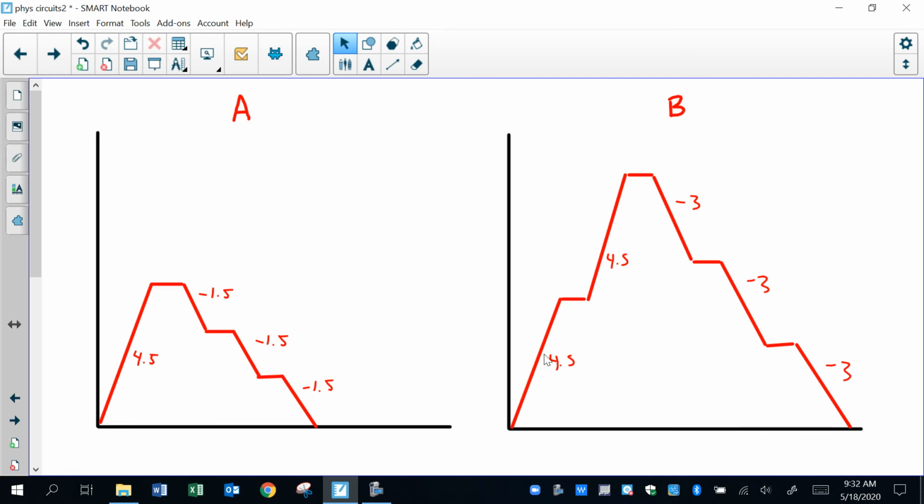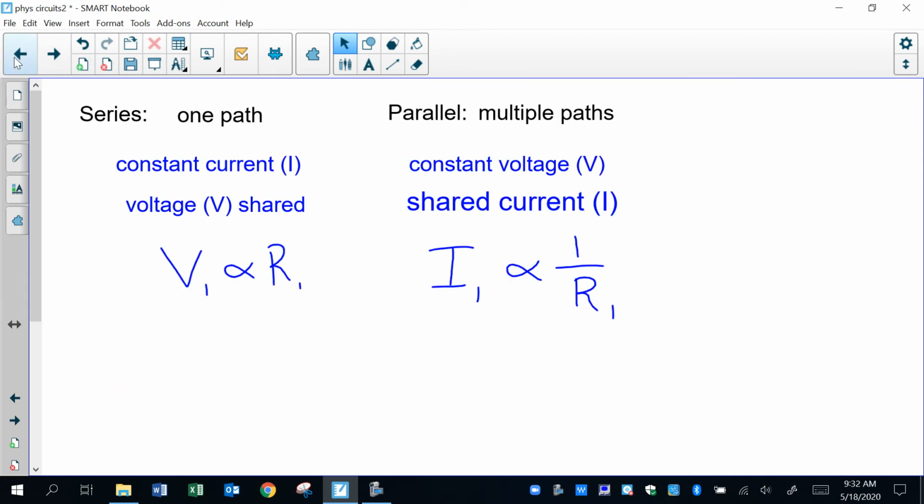This was an example from a worksheet if I had 2 battery packs. All right, I get 2 battery packs, 4.5 and 4.5 gives me 9. There's 9 volts for the light bulbs to share because they are in series, they will share. Now, this right here tells us if they're sharing, who's going to get the most voltage? If I have 9 volts to share, is it always going to be 3, 3, and 3? Well, it depends on your resistors or your light bulbs.